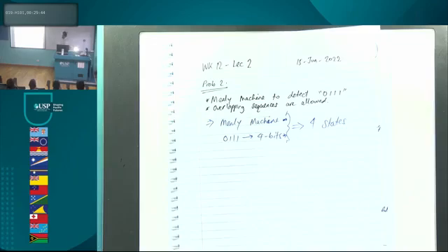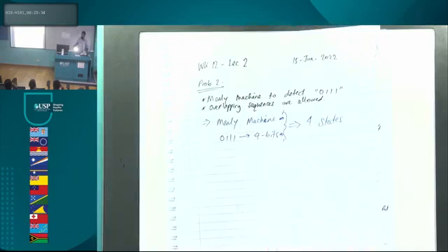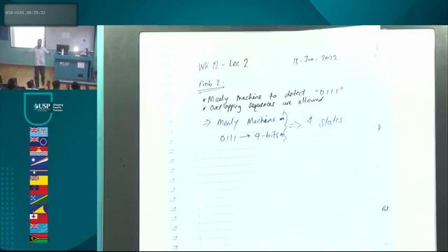Now, we have 4 states. If this question was changed to a Moore machine, so note this down so that you have an awareness, the answer would have been 5 states. What does 5 states mean, guys? That means in our state diagram, how many bubbles, how many circles will there be which are actually being used? 4 for Mealy.